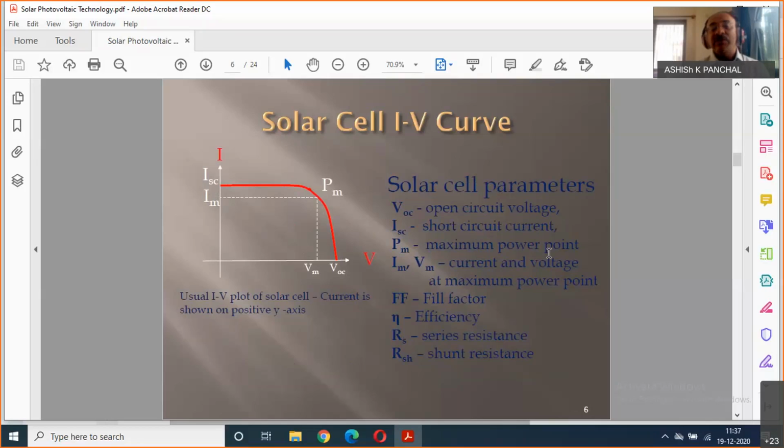Okay. And I am always interested in the maximum power voltage of the panel. Okay. Remember that I will not run my panel without this maximum power point. And also you need to remember if light changes outside, if the temperature changes, this maximum power point is going to be different. It goes to another value. It is heavily influenced by light intensity as well as temperature.